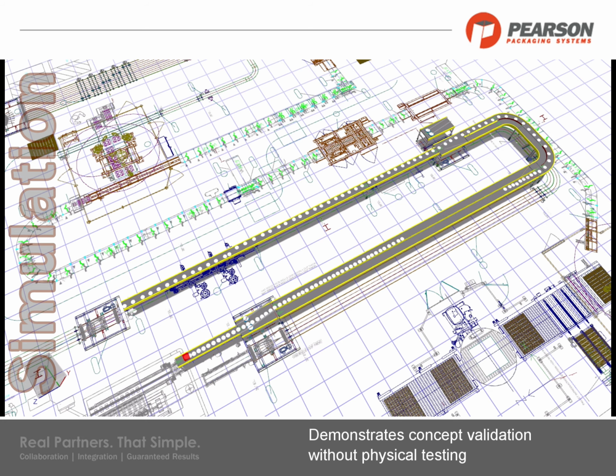We can see that we've got 60 products that are feeding in very quickly, again in that 7-second period. And then they station and hold there while the previous cycle was completing. After the 10-second dwell, we can see we've got another 60 products feeding in an adjacent lane. As that makes it to the end of the conveyor, it pauses and waits, and now we're in this long dwell period as we continue to discharge the material at the 12-inch spacing that was required for the customer, all in a single line of product.